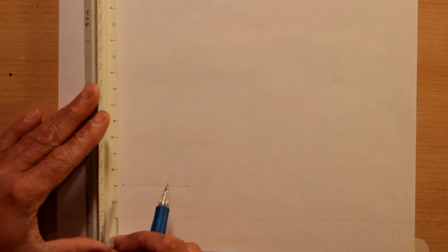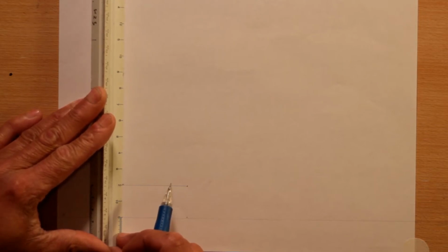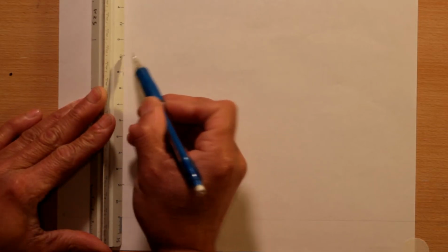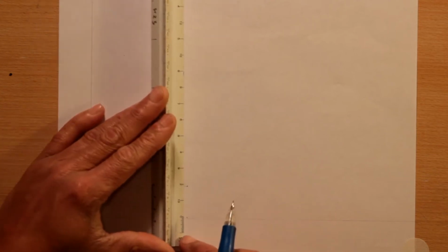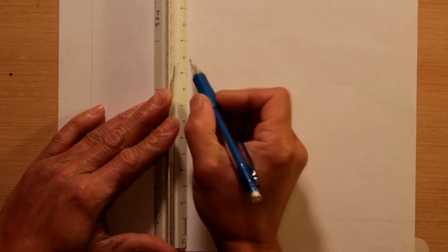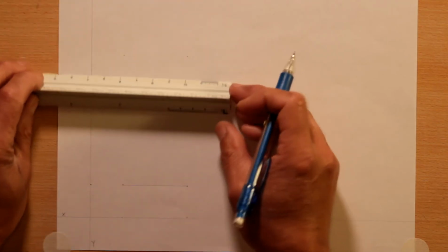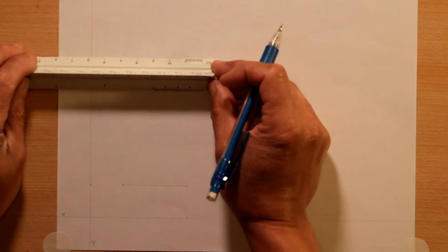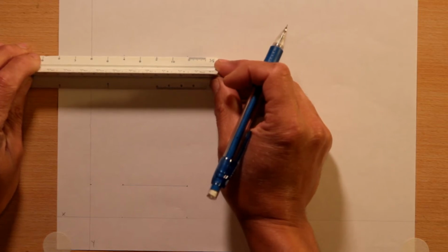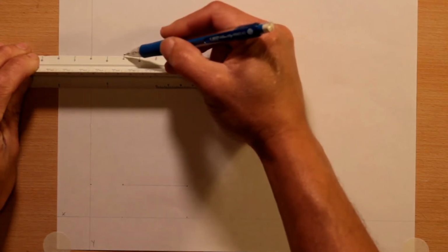Now, using 0 on your ruler, measure up vertically from the first tick you made on the X axis 10 feet and make a tick mark. Go to the second tick, which is on the X axis at 6 feet. Using 0 on your ruler, again measure up vertically 10 feet and make a tick. Now move your ruler horizontally, connecting the two tick marks, placing your ruler 6 feet on the y-axis. Draw a straight horizontal line starting at 4 feet on your ruler and stopping at 0.